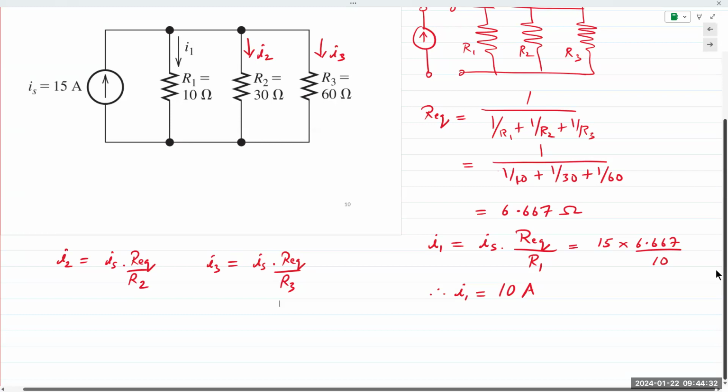There could be certain circuits like that. So the question being asked is when would we use this? And the answer is it just depends on each individual person. As always, there might be multiple ways to solve a circuit. So you could have 2 parallel lines, 3 parallel lines, or 4 parallel lines. You would determine the voltage across that network, and you could just find current that way. Some students like to do that.